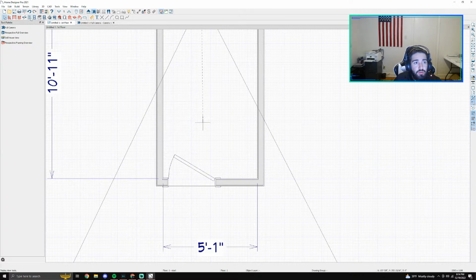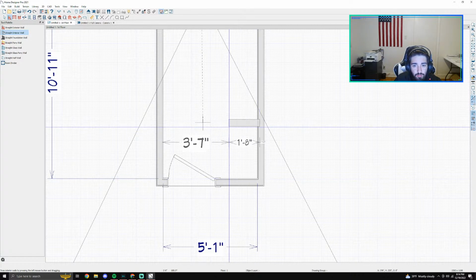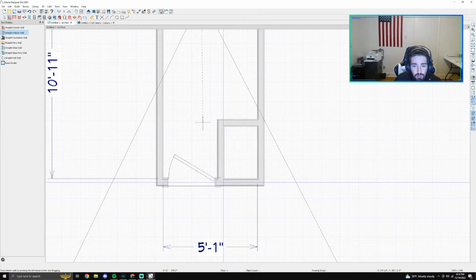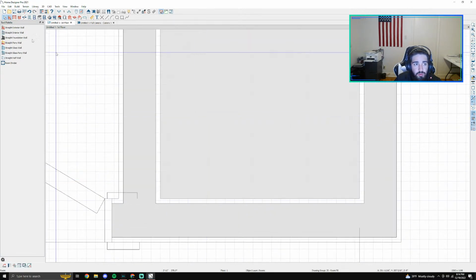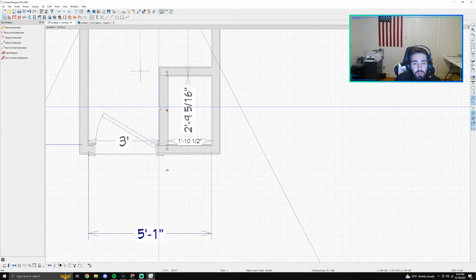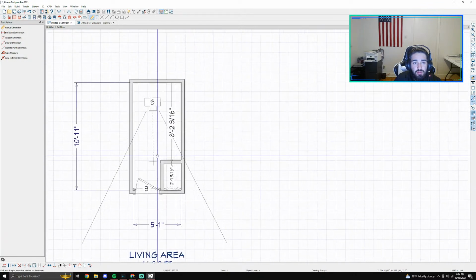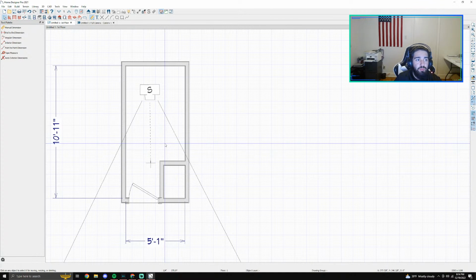Next thing we're going to do is another interior wall because there is a slight closet in here. So we're just going to grab from here and here. And this is measuring from the stud wall. What you notice right there is when I click this, it'll automatically create dimensions for the space. To get rid of that, you just press space, and then boom, it temporarily makes it disappear. Once you click on a wall again, it'll show back up.